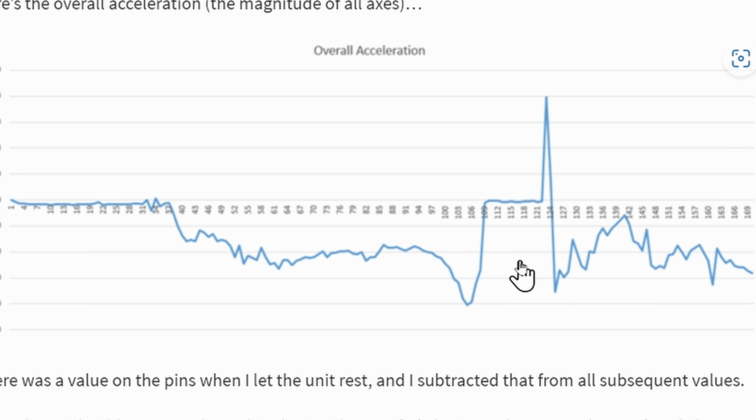I guess I need to look up how accelerometers work, because let's say you chuck it in the air, you're not chucking it perfectly flat. It's going to spin and turn a little bit. Spinning and turning shouldn't do very much inertial change on the chip. Some of the sensors in your iPhone are good at determining when it's been rotated, but that's not what this one is doing. This chip is only measuring how quickly you moved it in X, Y, and Z directions, and in this case, it's putting all 3 together.